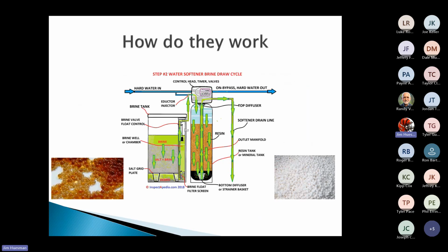So big one is, how does a water softener work? What is going on inside these 2 tanks that is allowing this water to go from a high calcium deposit water to pretty much no calcium whatsoever? What's happening is, and I know these arrows are going to screw you up a little bit, I apologize, water is actually going to be coming in. Forget the arrows, it's going to drop down this dip tube, run through our screen, and then enter more of a gravel base, okay?